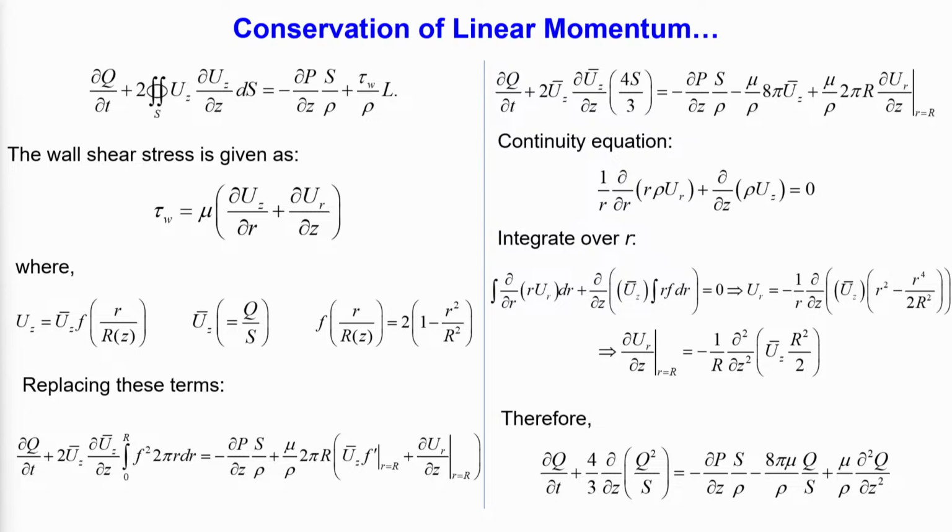and in that you have a velocity gradient at the wall, and to get the velocity gradient at the wall you integrate the continuity equation in the differential form, and from there you will get the value of velocity gradient at the wall in terms of the average velocity. And why average velocity is important? Average velocity is simply the flow rate by the cross sectional area. So, you can write everything in terms of the flow rate, which is your, as I told, the interesting hemodynamic parameter for a doctor, pressure, flow and resistance.